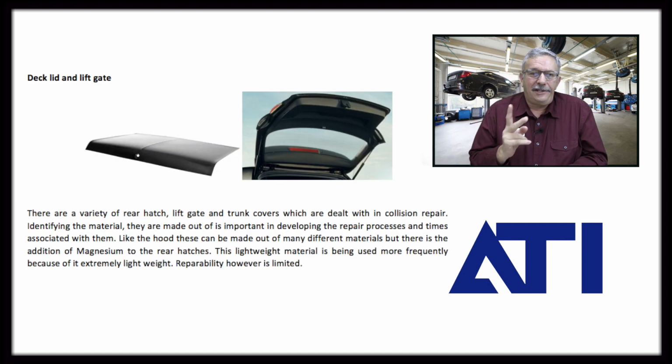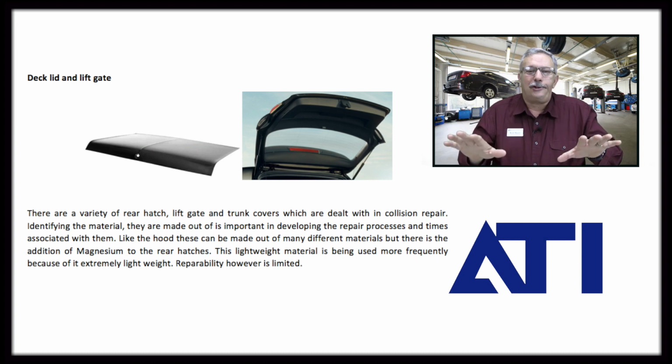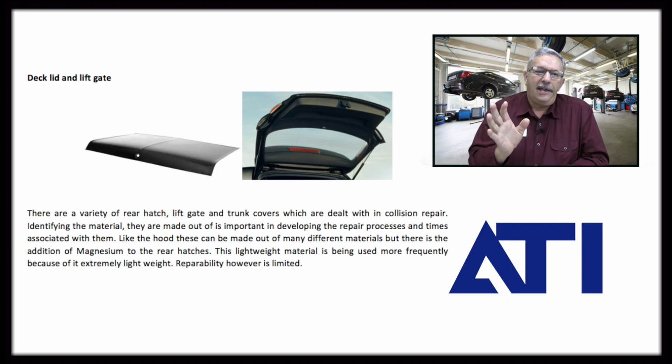Okay, the next, it's actually two items, but the deck lid, which we always called a trunk lid, and then, of course, the lift gate, which you have on your SUVs and minivans. Some things that are interesting about this. Now, the deck lid itself, the trunk lid, not a whole lot of changes in how those things have been constructed over the years. And for the most part, with the exception of some of the Japanese cars, you'll see that is becoming more and more of a high-strength skin that they're using. So it does change a little bit of the repair parameters.